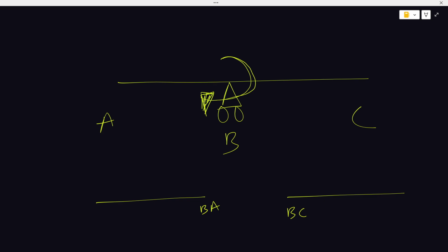And it helps us to do that based on the member stiffness, the bending stiffness that we just derived. Without the bending stiffness, it can't distribute. That is, it proportions the distribution based on the stiffness of our member portions. That is it. Please know this.